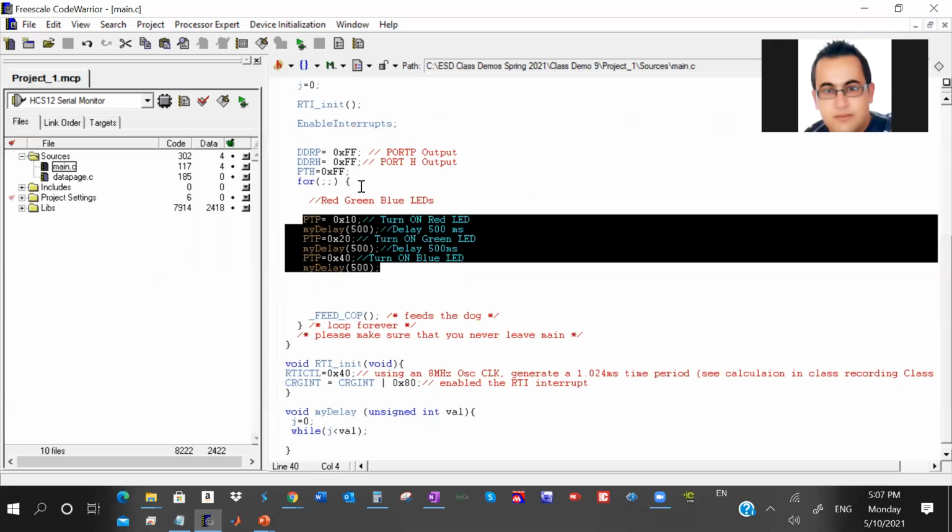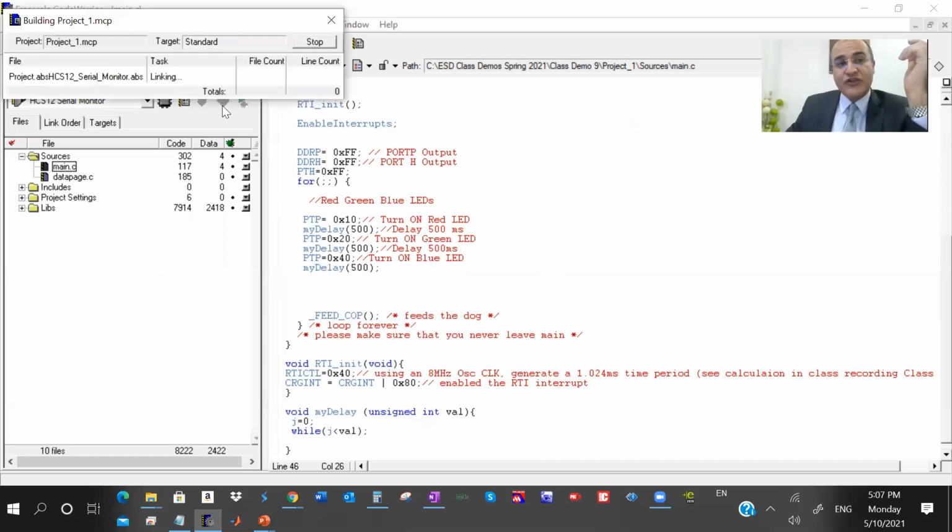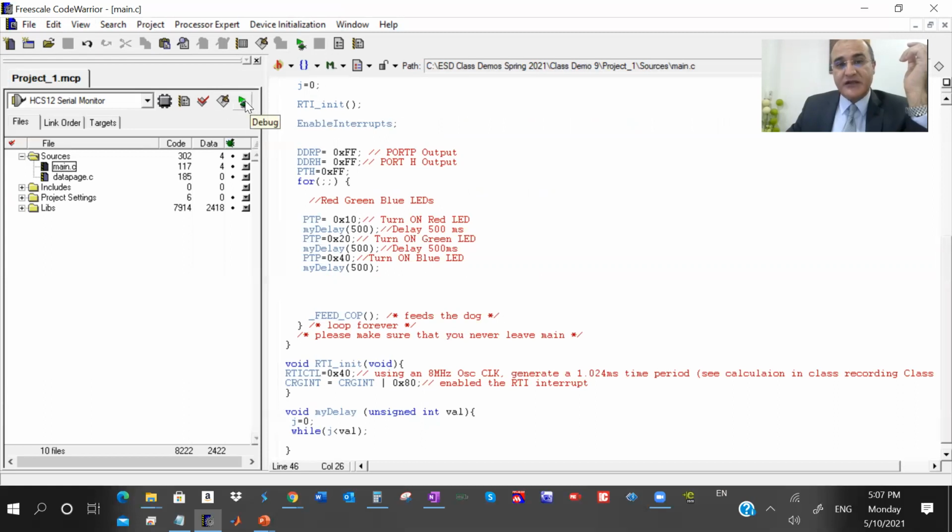Doctor, wouldn't there be interference here with the timing? Say every 10 milliseconds, and these instructions might take more than 10 milliseconds. Yeah, this is your responsibility as a designer. Yes, you need to know that. You need to have an idea, or if you don't have an idea, go see the equivalent assembly and see how much this code takes.